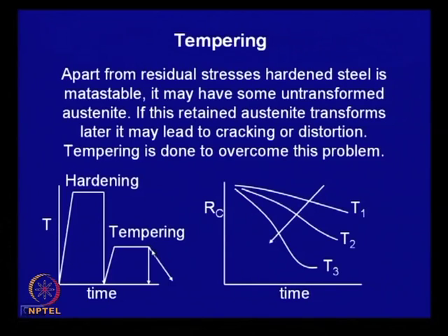And after tempering, it does not matter, you can quench, because you want a higher productivity. You can quench in oil or water, or you can let it cool in air. Now, the process of tempering,